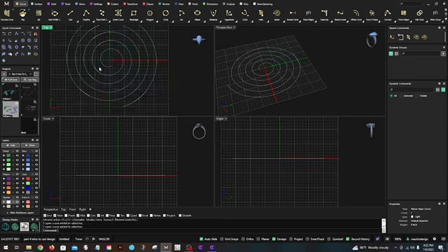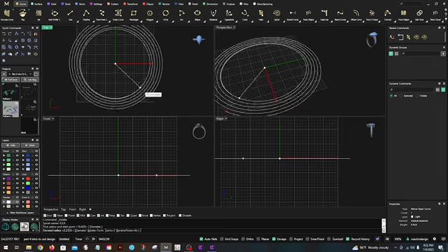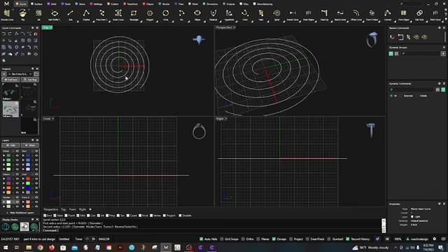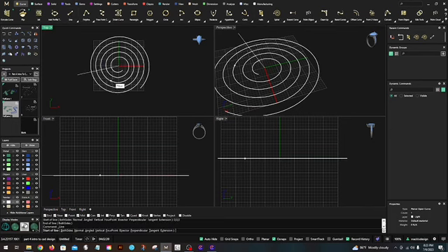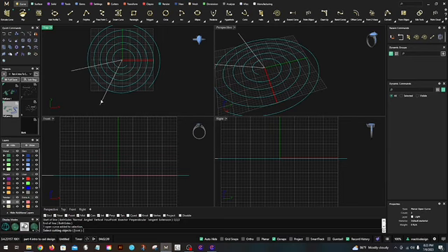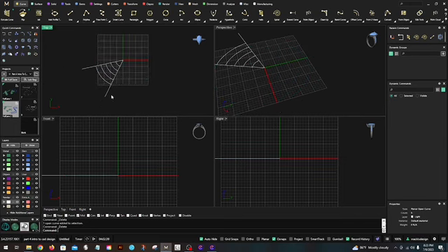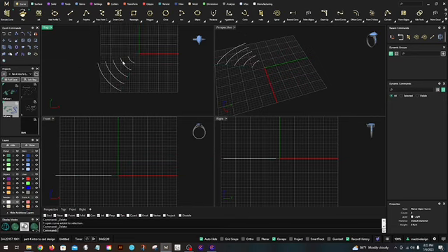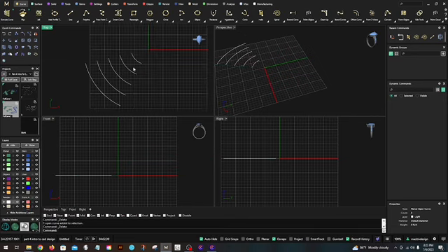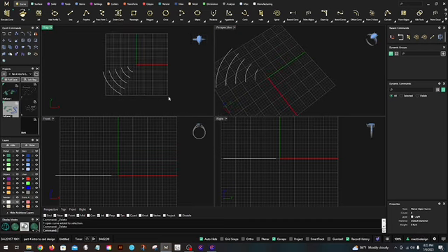Definitely. And you know what's nice about this? If you did a spiral that was flat and you wanted, let's bring in a line and another line, and I'm clicking F4. Take your spiral and let's split it with these curves. I don't know if it will. Yes, it did. Yay! Delete, delete, delete. All right. And let's just say you needed some curved lines that were exactly the same distance apart. This is a really quick and easy way to accomplish that.